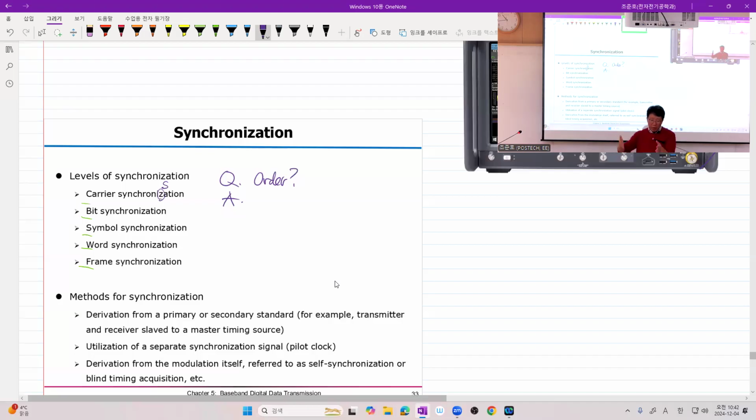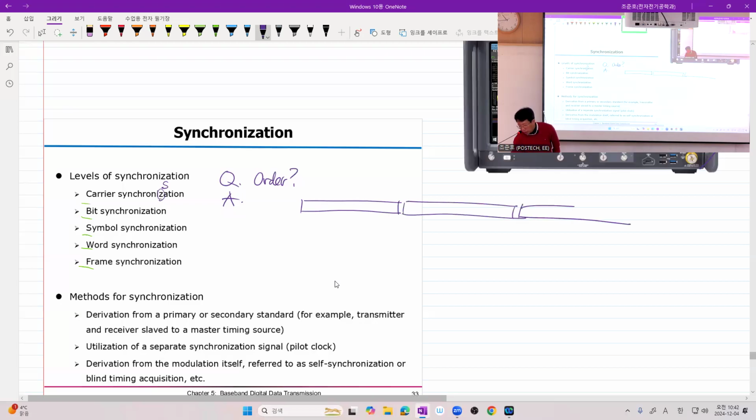And timing of each symbol, the exact sampling offset, is also called synchronization. Sometimes if you have many bits put together, then this timing is called recovered if we have, for example, slot synchronization, sometimes frame synchronization. This terminology depends on different standards.